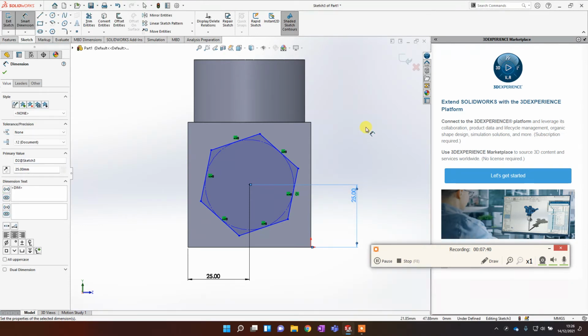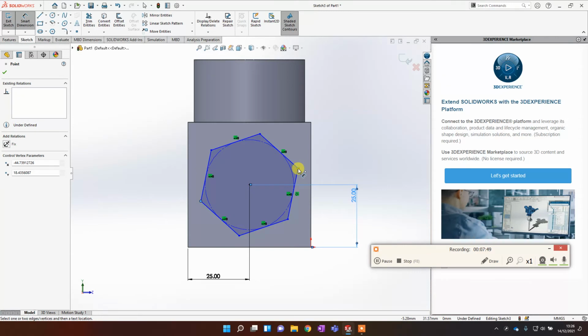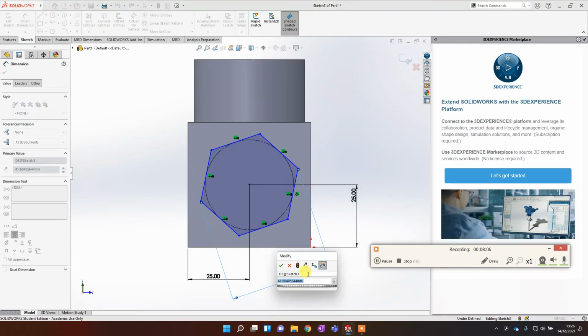Okay, I'm also going to make my hexagon a particular size, and I'm going to determine that from point to point. So I'm going to put my dimension tool between here and here, and notice you've got to be a bit careful here. Can you see if I'm in that mode it says 39.48? However, if I come over to the right a little bit, that's the true parallel dimension, that 41.6. So that's the one I want to place. And I want you to make this one 45.